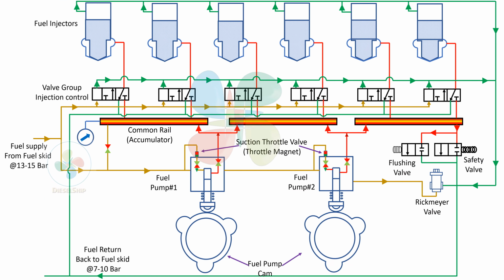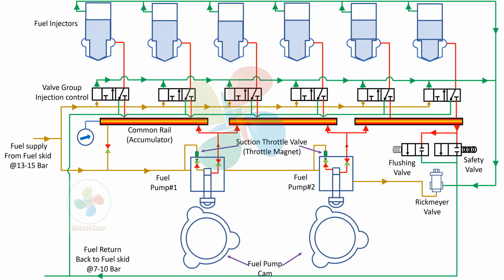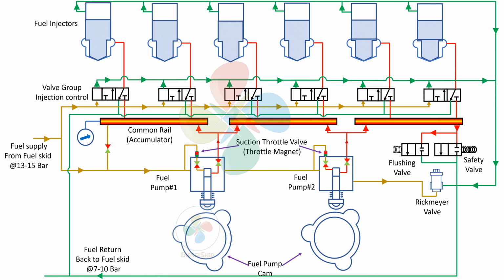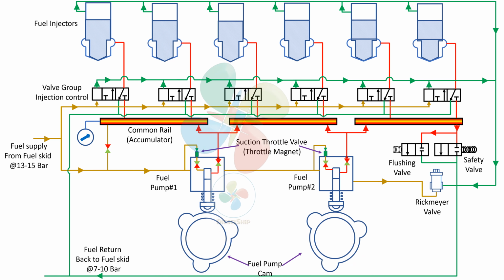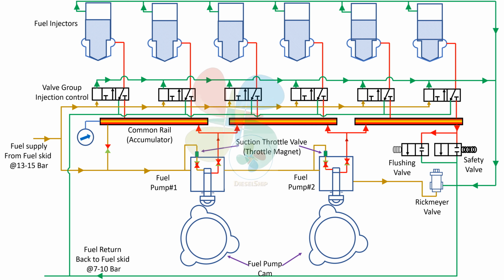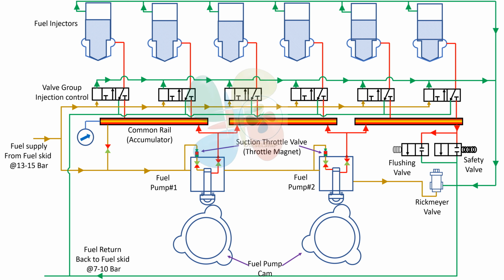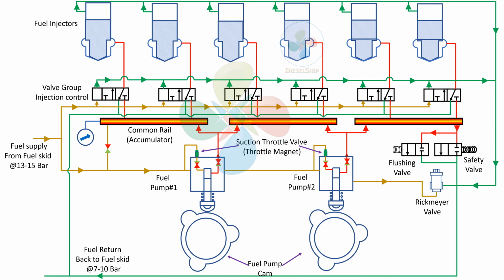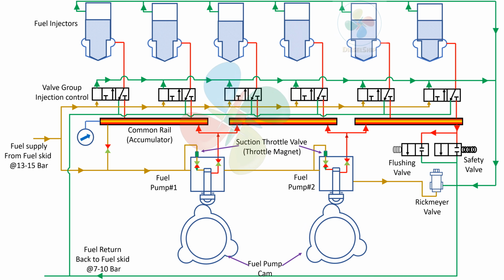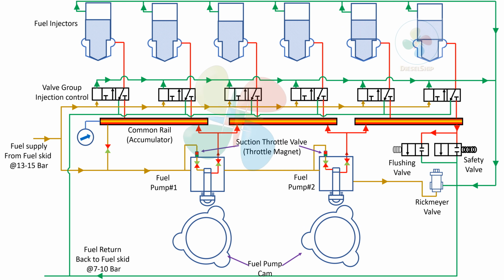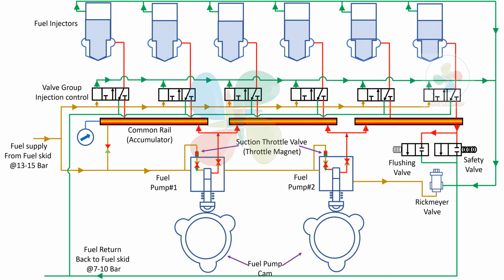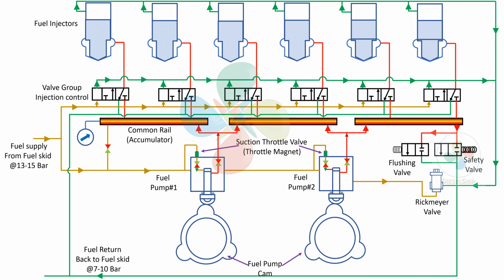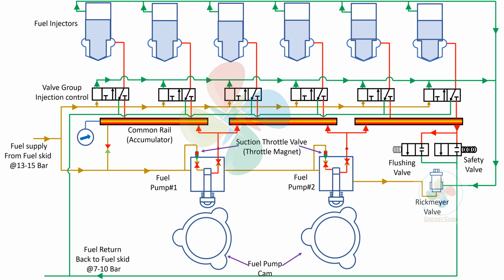Let's now simulate starting the engine, where the fuel will move through the pump to the accumulator, through the valve group, and to the injector. Commencing of injection is very important. That timing is very, very important for a valve group. At the same time, termination is also very, very important. When the fuel starts injection, basically it moves into open for a few microseconds. And when it has to terminate, the fuel has to drain down. So you can see all that in this animation.